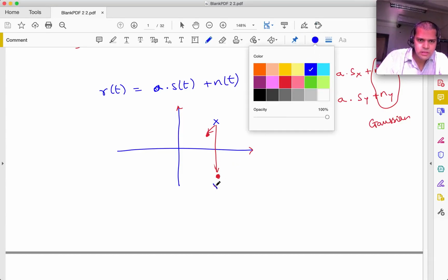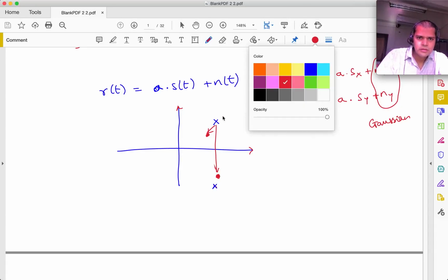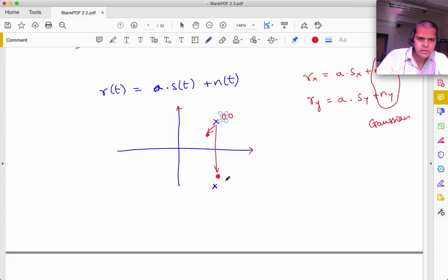So there is this other constellation point, and we said that here we had bits 0 0 and here let's say 1 0. So if this constellation point gets pushed to this quadrant, from the first to the fourth quadrant, notice that the second bit is not in error.